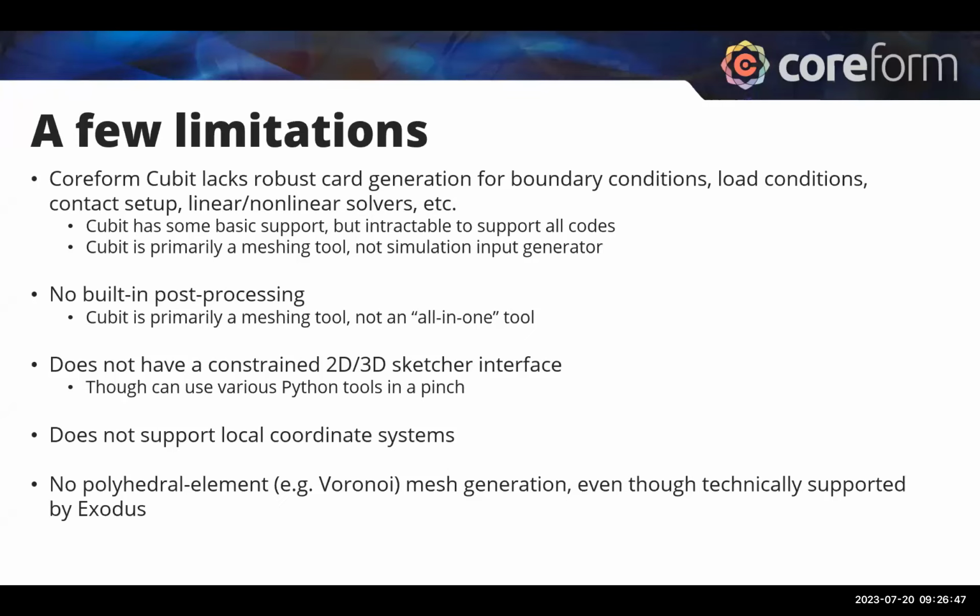One thing is that Coreform Cubit does lack robust card generation for boundary conditions, contact, and setting up linear and nonlinear solvers and physics problems. That's primarily because Cubit was built to be a meshing tool. In certain cases, we've added some generic functionality for these conditions, but all of the different simulation codes out there have different names and terminologies, different ways they apply these different conditions.